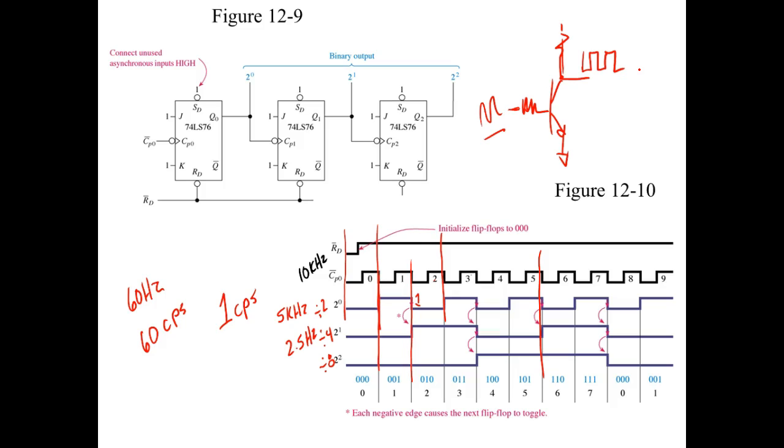That's why all your frequencies are weird, like 1.1, 2.1 gigahertz, right? If you actually looked at the true frequency, you would see it would be a multiple of 166. So they just take that high frequency and divide it down. So we can use counters as counters, or we can use them as frequency dividers.